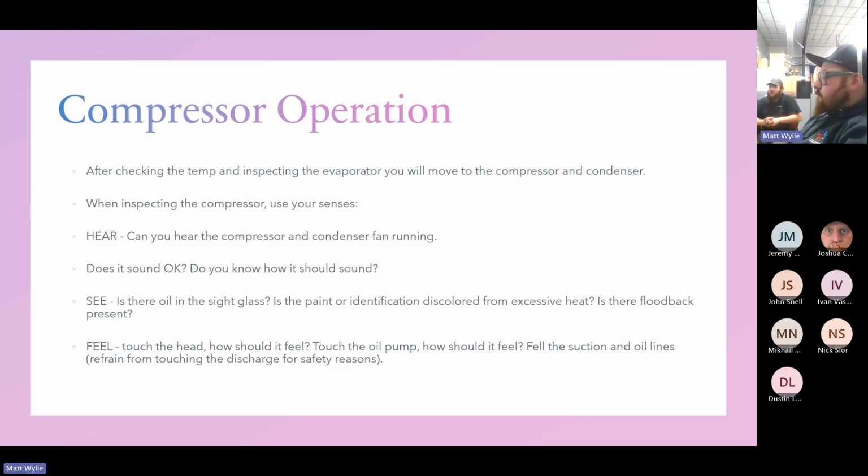On that note too, I've also seen voltage drop across fuses on disconnects. Not very common, but I have seen it. Yeah. Which probably indicates either a weak fuse or your fuse holder is not making a good connection. Resistance. Yeah, it's usually the fuse for me.